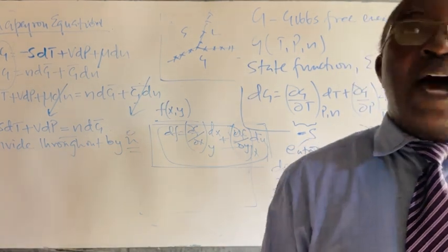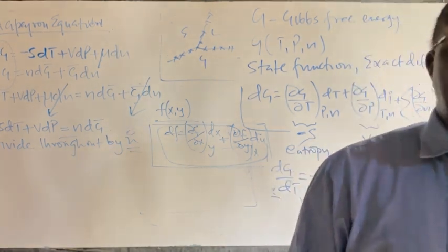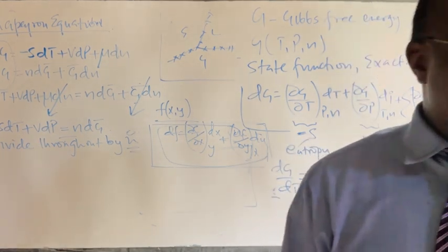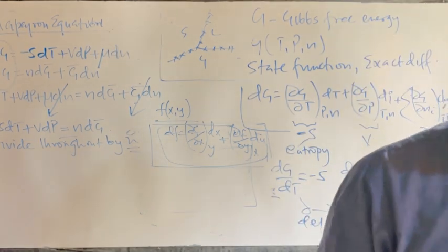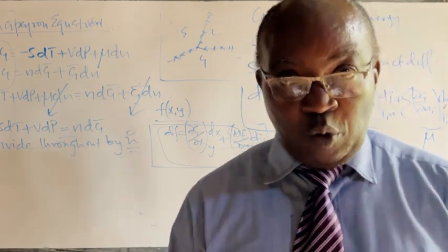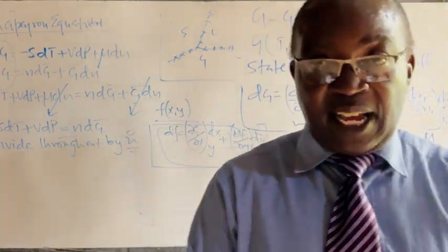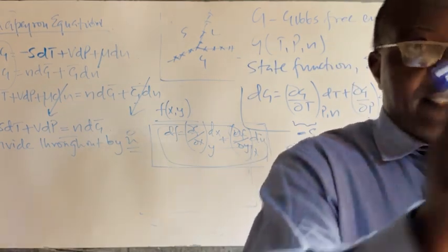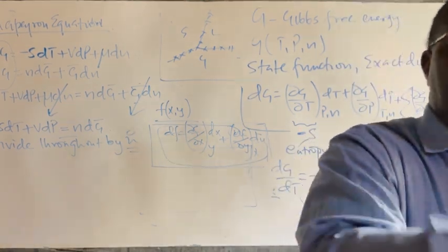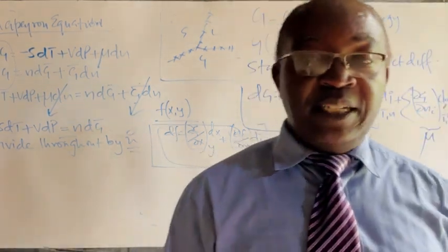And how does it come in? We said if the enthalpy is negative, that's an exothermic reaction. Heat is being released, so you must be able to know what to do. If you're using a batch reactor, you must use a continuous stirred tank reactor, for example, where you are able to lag your system and allow water to move around it to cool the system, because there could be a lot of heat generated.